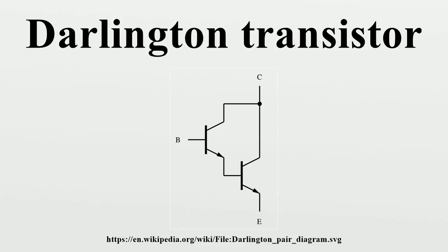Another drawback of the Darlington pair is its increased saturation voltage. The output transistor is not allowed to saturate because the first transistor, when saturated, establishes full parallel negative feedback between the collector and the base of the second transistor. Since its collector-emitter voltage is equal to the sum of its own base-emitter voltage and the collector-emitter voltage of the first transistor, both positive quantities in normal operation, it always exceeds the base-emitter voltage. Thus, the saturation voltage of a Darlington transistor is 1 VBE higher than a single transistor saturation voltage, which is